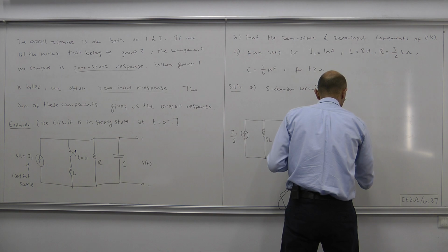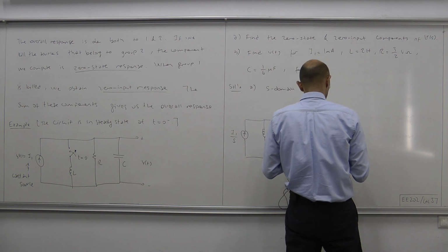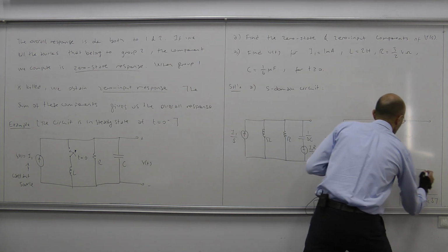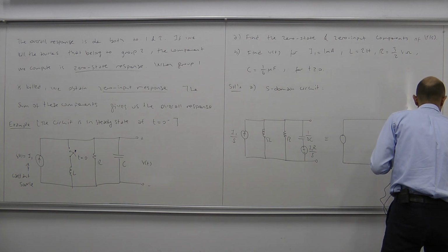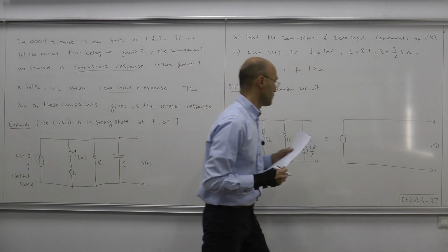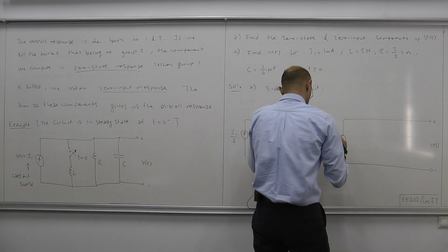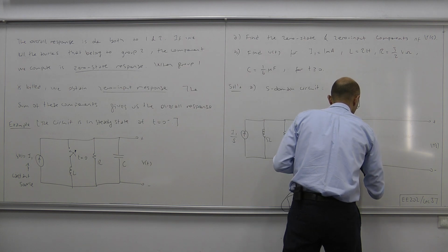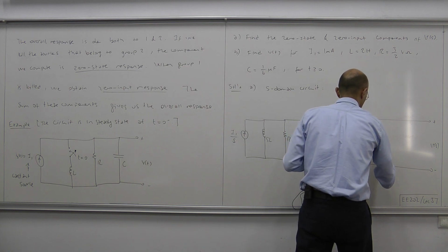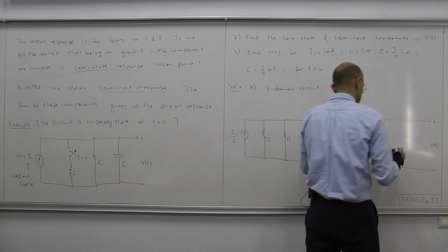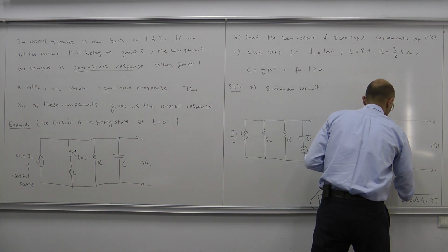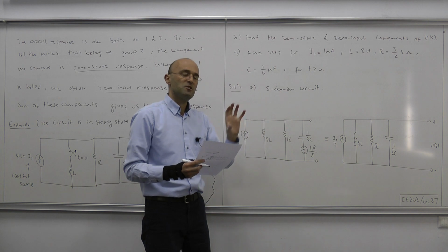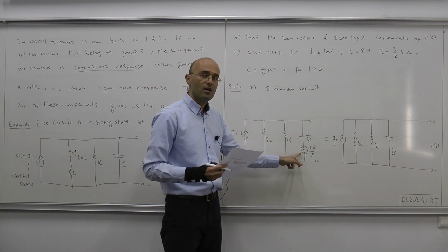So after that transformation, we have the following equivalent circuit. And here, this is our voltage that we're looking for. Okay, this is I1 over S. And here we have SL. Here we have our resistor, R. And then this is our impedance, 1 over SC for the capacitor. And now the initial condition of the capacitor is being represented by a current source instead of a voltage source.